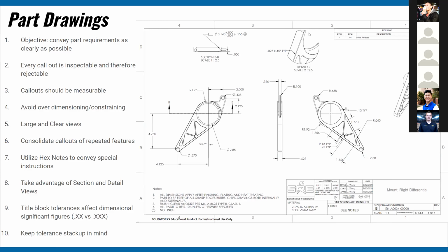There's other stuff I haven't really gone over on the drawing. So like this revision block, I think that's pretty self-explanatory. That's Rev 01. You want to put in simple descriptions of what the revision is doing. In this case, it's an initial release of this part. Other times, say if I had to fix the dimension on a hole, you just say that, then the description of what that rev is, and then obviously the date and who it was approved by.